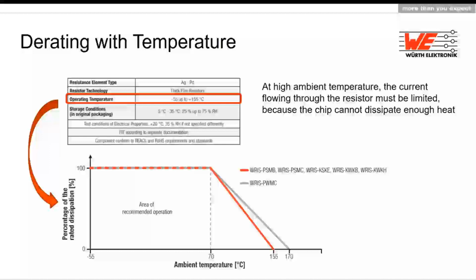About the derating, you may have seen in the datasheet before that the operating temperature is stated up to 155 degrees. But if you look in detail, there is another specification in the datasheet, the derating curve of the rated power. Regarding the limit of too much current flowing when the ambient temperature is already too high and the heat energy may not be extracted for safe functionality and stability, the terminal part temperature, which reflects such influences accurately, is more suitable as a reference for the power rating of the resistors. When you monitor the temperature of a terminal, it prevents the part from damage and allows you to select the proper size and number of needed resistors for your application. So it is really worth doing, not only to check a hotspot of the part, but to monitor the complete terminal temperature rise.